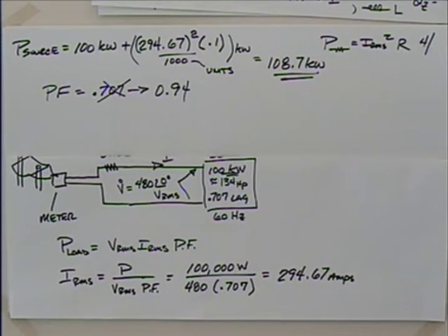If you look at where power comes into large industrial settings, sometimes there are these great big boxes up there. Those are capacitors, and they're trying to fix their power factor. If our motors are about worn out, maybe we want to sit down and say, hey, maybe we can buy motors with a different power factor. And that's an economic decision.